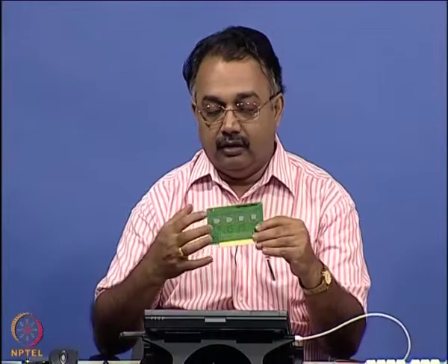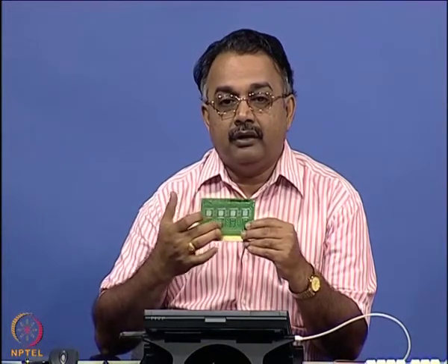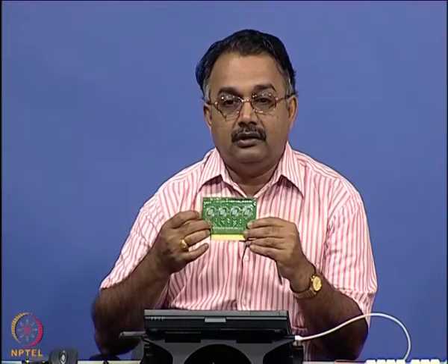Similarly, when you talk of a board or an IC here, during its operation, if there is a crack on the silicon die or if there is some copper interconnect that is breaking up during the process, that means there is some problem at the design level when you have manufactured this system, subsystem. Okay. So, you have to build in reliability at the design stage itself, so that your throughput is large, yield is large and the time spent for repair and rework is very minimal.